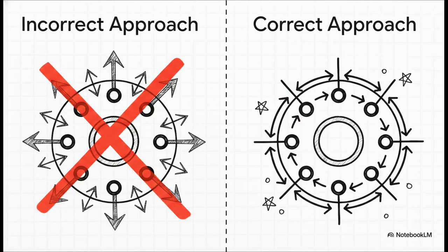But here's where the basic framework hits a wall. Standard position tolerancing treats every single hole as an isolated, independent feature. And when you're manufacturing something complex, like an engine block, a hydraulic manifold, or a precision aerospace flange, treating holes independently completely ignores functional reality. It fails to control the relationships between multiple holes. We need to control how the entire group of holes locates to the part, sure, but we critically need to control how the holes relate to each other. Relying on a single positional tolerance often just over-restricts manufacturing and drives up costs without making the assembly any better.